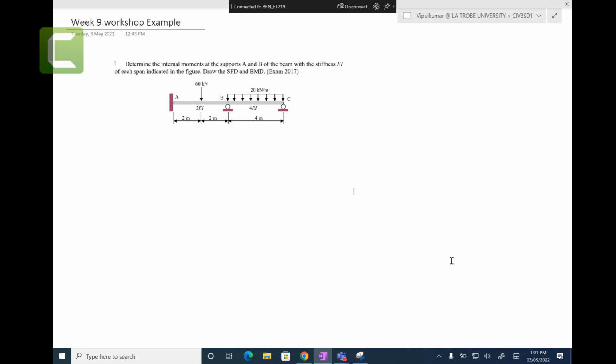Last week we studied force methods. All these force methods and displacement methods are used in solving indeterminate structures, meaning there are more unknown values than equilibrium equations. You can't solve those questions by equilibrium equations alone, as you know from last week. The advantage of these displacement methods is that they can be used when you have multiple spans, where the degree of indeterminacy is quite high.